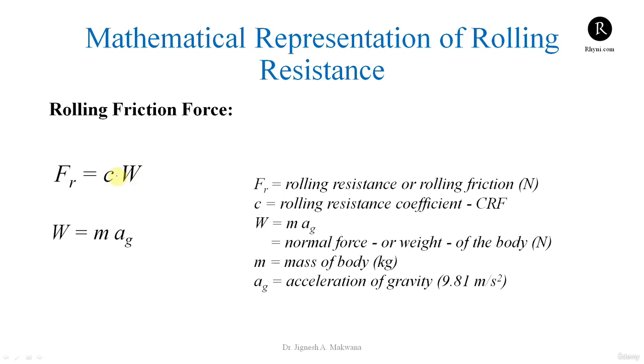So it can be neglected in some cases like the bicycle and bike, but when the width of the tire is increased or rubber tires are there, it will be slightly more. So we can simply add this opposing force to the equation that we developed already and to the simulation model also. We will do the simulation with this rolling resistance coefficient and we will also check different conditions. So this is one more opposing force we are going to add in the equation we have developed.